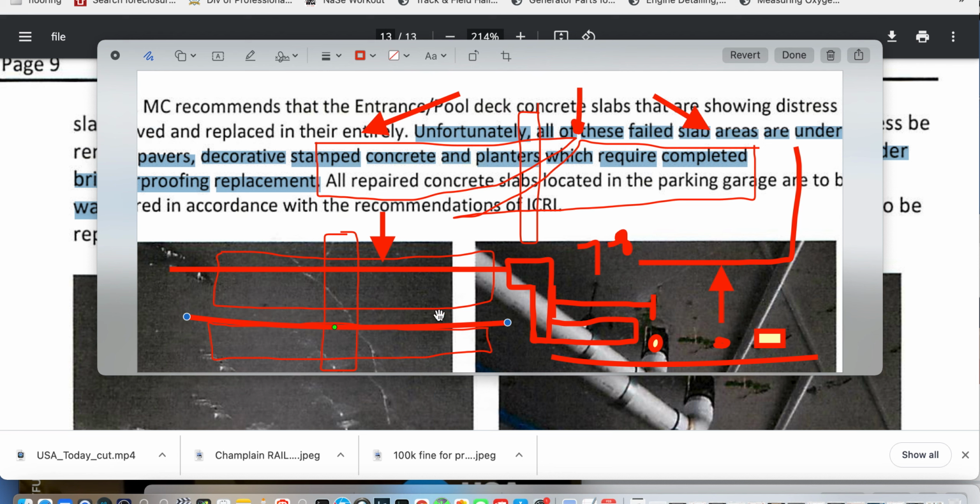Yeah, we had a core sample that I ruined doing it. Let's play devil's advocate. I somehow made this core sample look this way, but I didn't make the walls that I cored down look that way. So let me look into it from top and bottom. Oh, and sure enough, the walls are perfectly smooth. Huh. Somehow I was able to manage to break up this core sample. I must have had the drill on some type of weird hammer drill. Nope. You look into that hole and you see the delamination, the profile matches. You're like, oh, we've got a deck that's splitting apart.